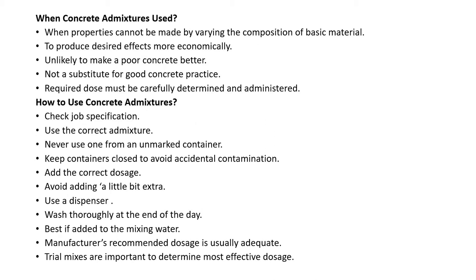Concrete admixtures are used when properties cannot be obtained by varying the composition of basic materials, or to produce the desired effect more economically. They are unlikely to make a poor concrete better and are not a substitute for good concrete practice. The required dose must be carefully determined and administered.